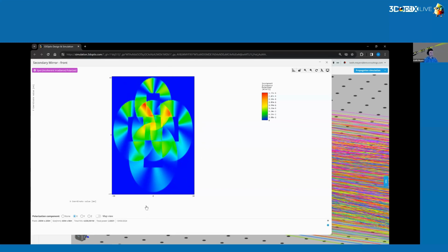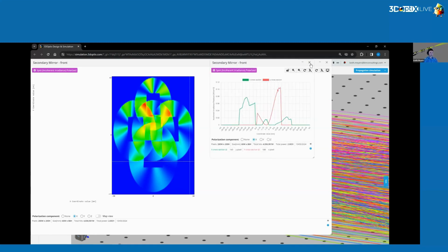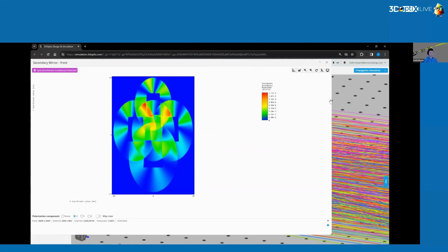So traditionally, you would use a parabolic shape, not a parabolic surface, but a parabolic shape to create this secondary mirror. As you can see, there's kind of a parabolic design to the fields of view. And this, again, minimizes the surface area of the secondary mirror so you can increase your light throughput. And that's really important because it is blocking a substantial amount of light. So we want to remove as much material as possible.